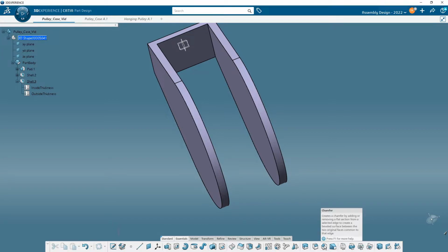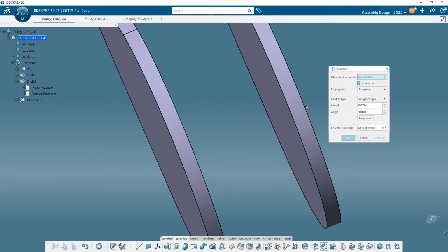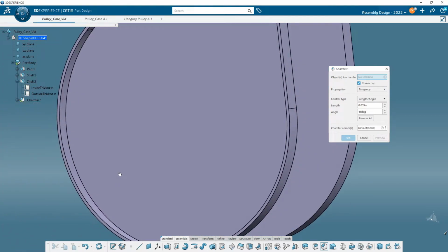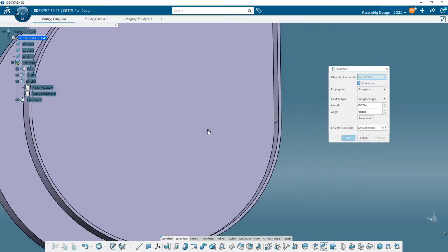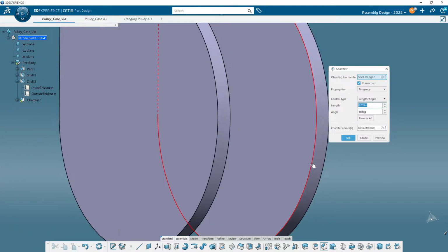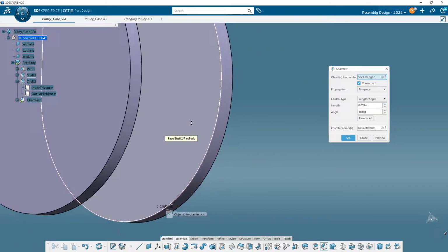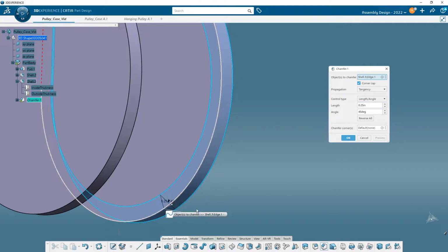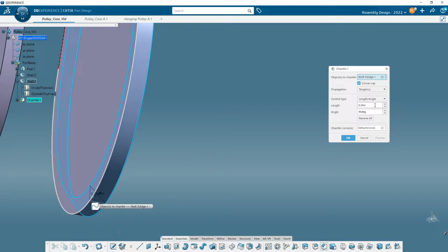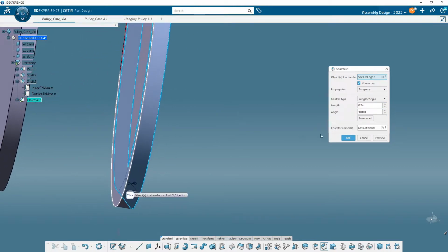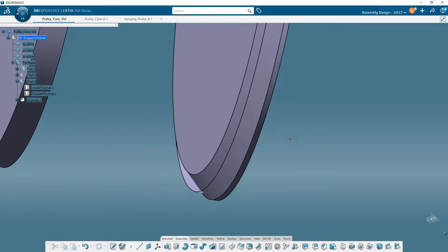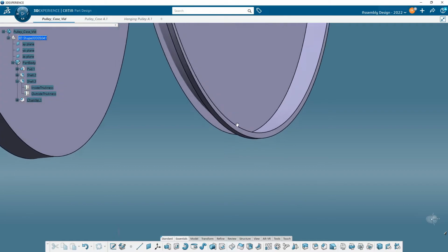And then I come over here with the chamfer tool. And so see what's going to happen here is I'm going to chamfer this side, but just because you chamfer one side doesn't mean that you chamfer this other side. So a lot of bizarre things could happen. Most probably not good. So I'm going to say that this is 0.25, so it's the whole width of the thing. I hit preview, and you can see it's going to go up there like that. No, let's not do that. Let's go 0.2, so it'll be a little bit shorter. Preview, right? Then I'll hit OK, and now look what we get. This is an impossibility.